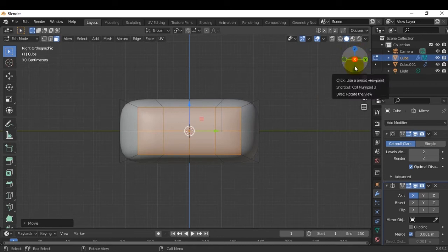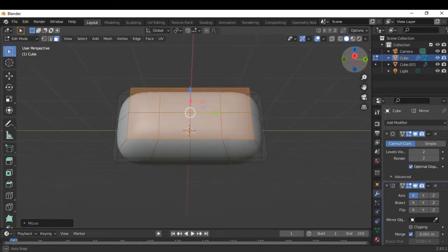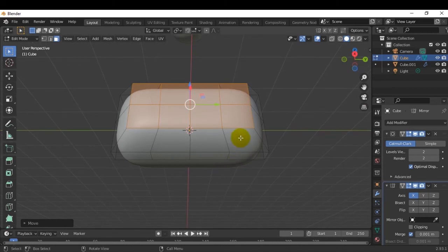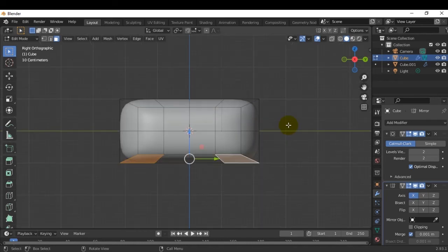click and drag here, click and drag upward slowly so as to display our bottom section here. Now make sure you're in face mode, so select this face and then hold shift, and then select another face, select this another face. Okay, now go back to side view 3, and then we will extend that portion about 2 square units down here.